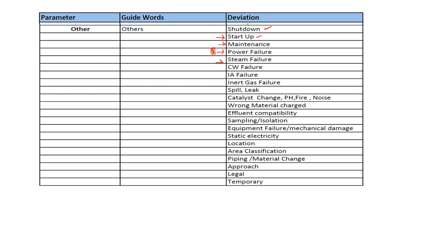And then steam failure. So the power failure basically gives you the risk of power failure, and from here people determine the load shedding schemes, how to shed your loads, right? So suppose you have two gas turbines, one is 25 megawatt, another one is also 25 megawatt, and one of them suddenly got tripped or there are some issues.